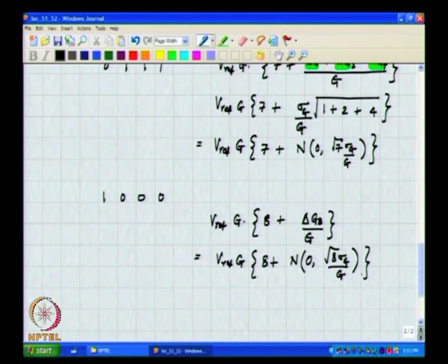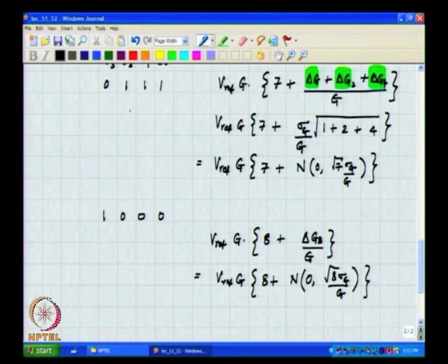All right. Now, in other words, if there was no mismatch, if the code changed from 0 followed by all ones to 1 followed by all zeros, then the change in the current should be Vref times D, which is definitely true, correct.